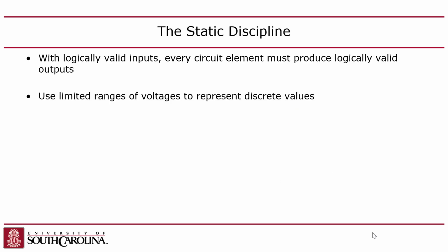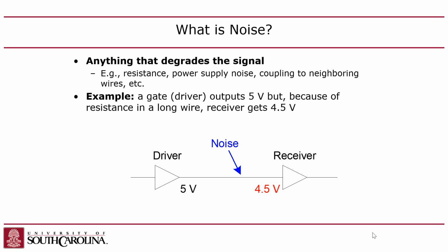So if you have noise affecting a wire, you just have to keep the noise below the difference of, for example, the VIL of this gate and the VOL of this gate, or conversely, you have to keep it between the VIH and VOH, right? Does that make sense? Okay, so that's the noise margin.